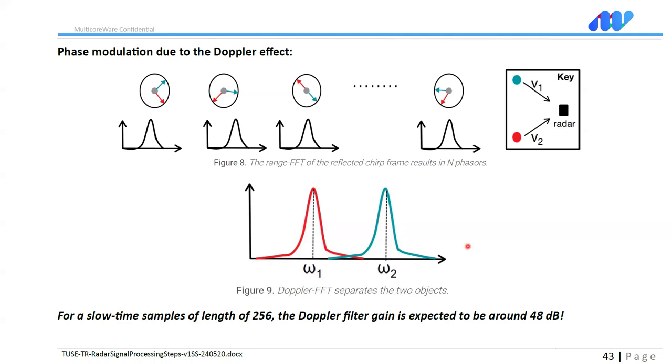But what I'd like to note here, an important note, is that you don't do Doppler processing just to measure the target velocity, and maybe not just to resolve targets, but also so that targets become visible. When you do the Doppler processing, you increase the signal to noise ratio of the signal once more. Range detection, range correlation give you some amount of decibels, and here you get another gain.